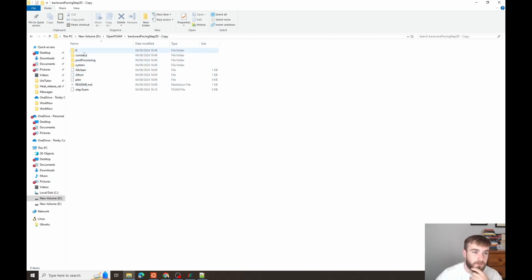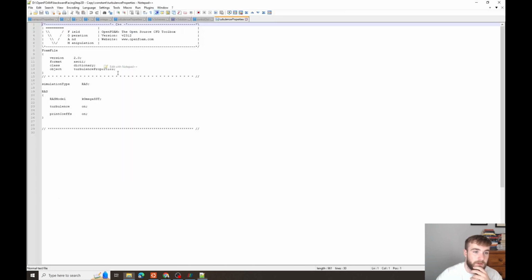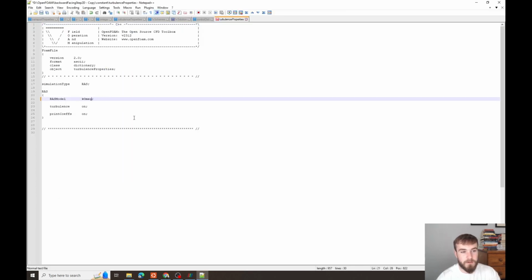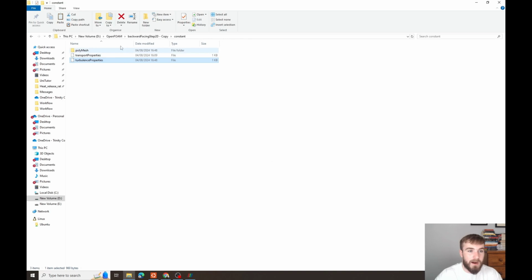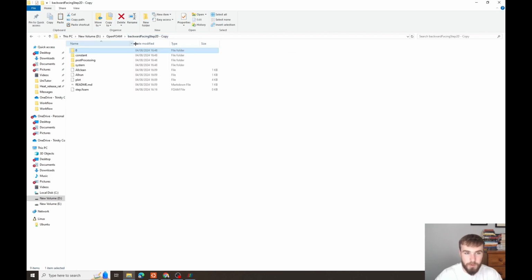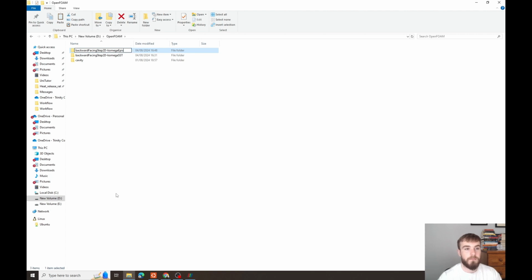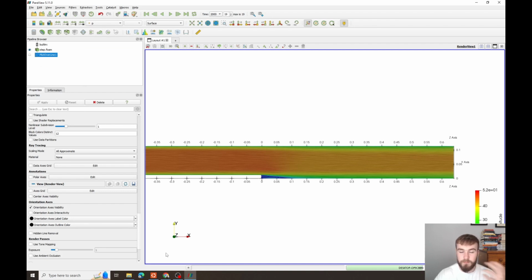Let's change the turbulence model here. So that's going to be in constant, turbulence properties. And you could try K epsilon here, because the epsilon conditions are defined in this tutorial case. There's an epsilon file here, so K and epsilon are defined at the boundaries. You will be able to run that case if you want to. Just note if you're using a turbulence model that's not fully defined in the boundaries, you will probably get an error, but it will tell you in the terminal that the turbulence model is not valid. Okay, so if you wanted, you could again run that case. You could compare the results between the K epsilon and the K omega SST,